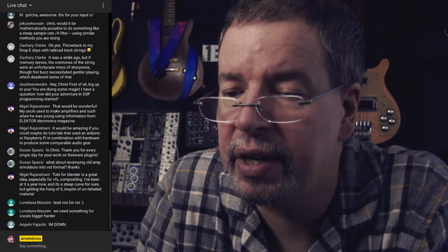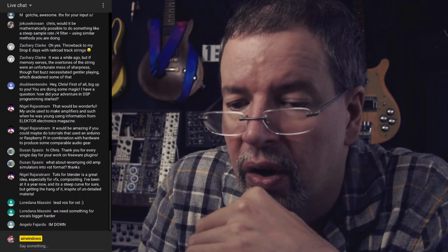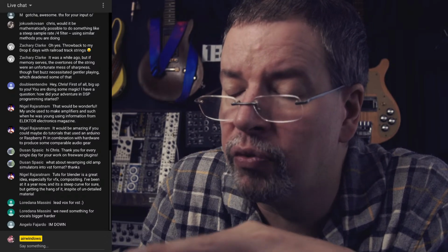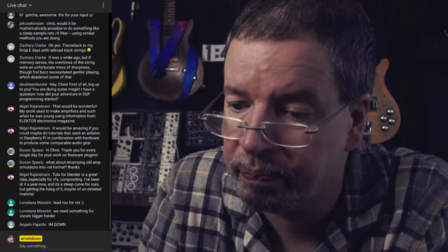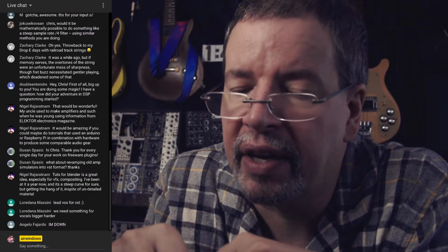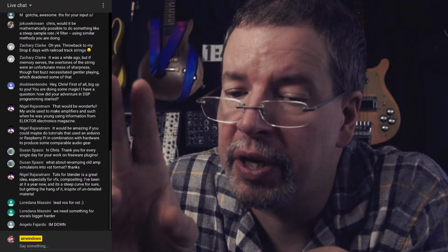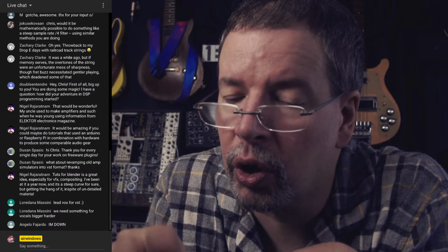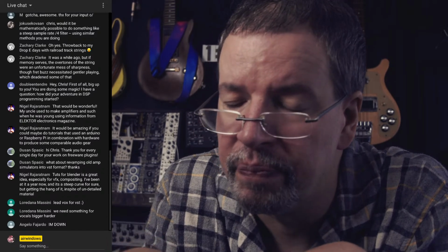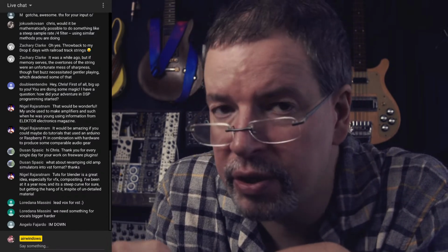And to feed it in, all you got to do is have some kind of little thing to trigger, override the loop section, so that you either are giving it a high voltage and forcing it to be on, or grounding it and forcing it to be off, regardless of what the feedback is trying to do to it. And that's how you do that stuff.